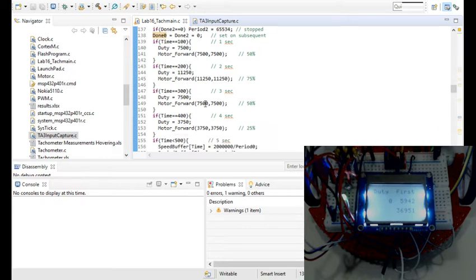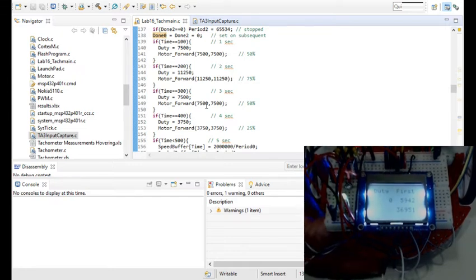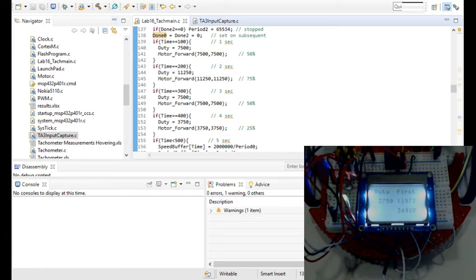So this is going to run, and I have it set up on here, so let me go ahead and reset that and then let it run. As it runs, you can see the duty cycle under duty is being set, and as the motors are turning, the other tasks are being set with the other timer, and it's collecting that information. So they're triggering an interrupt every time they go through, and it sets off an event, and then that's getting collected. They have another part of it that they're saving off to flash, and that value you can go and utilize, and they also do some calculations with it, because as you can see, the values are pretty random.